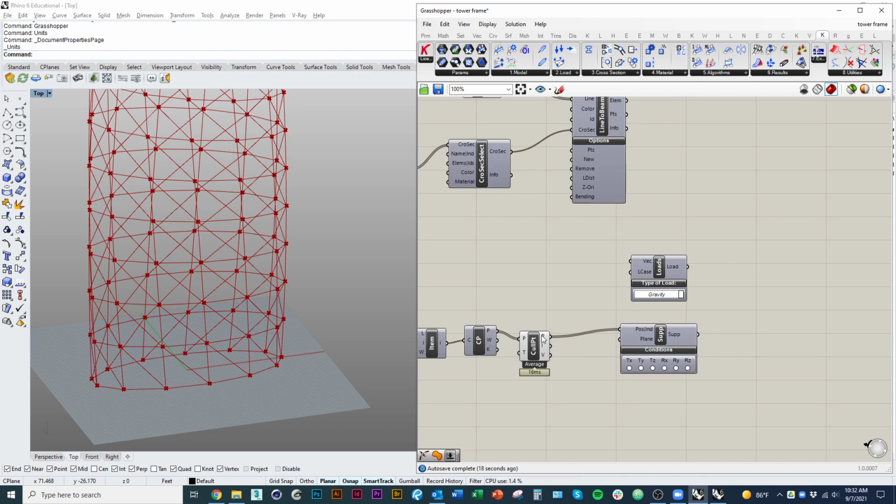What that means is that at each of these points, we're going to constrain movement in certain directions, right? We know that this point can't slide or shift, but we might not constrain it in terms of rotation. If we had something like a pin connection, that can rotate in some dimensions and not in others, so we can constrain the direction of the rotation.